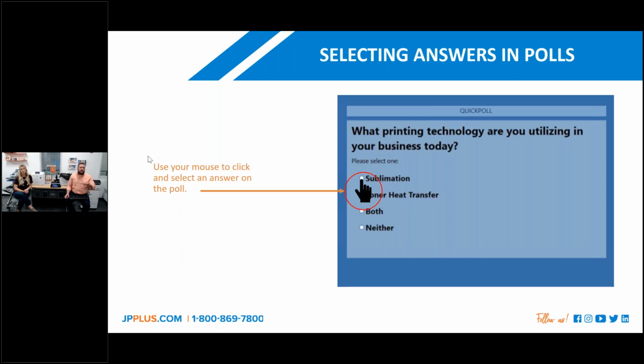So one, you'd want to know, are you getting even heat and consistent pressure? Because if you're not getting consistent pressure and even heat, that back part of that transfer might not be adhering appropriately. So that's part of the problem. The other thing is sometimes at the end of a peel, you almost want to let that end of it come off on its own. So just real gently, one slow, solid motion. So, we could talk to you a little bit more and see how you're doing and find out a little bit more about your press, but it's solvable, but there's just some variables there that we need some more information on.